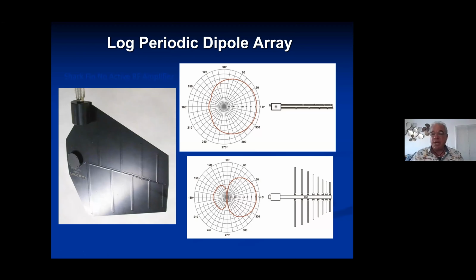Dipole's a nice basic antenna. It's always great to stick one in your backpack or in a rack drawer. Certainly nothing wrong with the dipole, other than it's kind of like a grandfather clock that hasn't been wound, or an analog wristwatch that's broken. It's still right twice a day, okay? But as soon as you go off axis with your RF transmit signal, you will get a dropout.